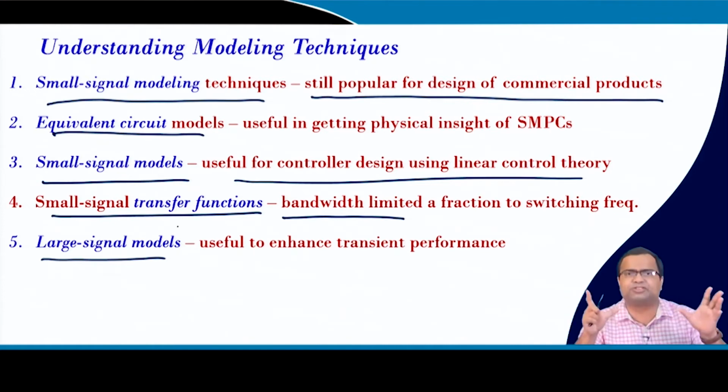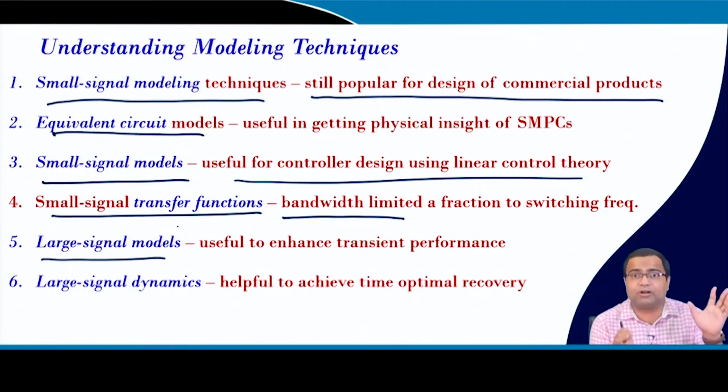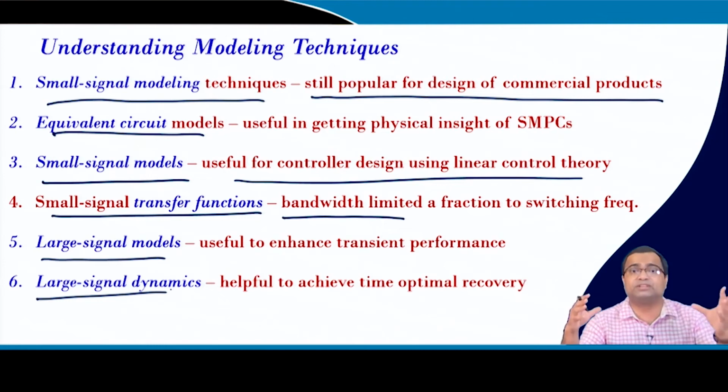So, for wide duty ratio variation this model can still work, but if we want to incorporate the switching dynamics, then you will get the fastest response, which is a time optimal recovery, and that is what we want to achieve in future, so that our power supply becomes extremely fast and very highly energy efficient, and it can meet the increasing demand of the different sites. So, that you can reduce the size of the capacitor, and we have discussed that such fastest, time optimal performance also allows us to reduce the output capacitor and increase energy efficiency.